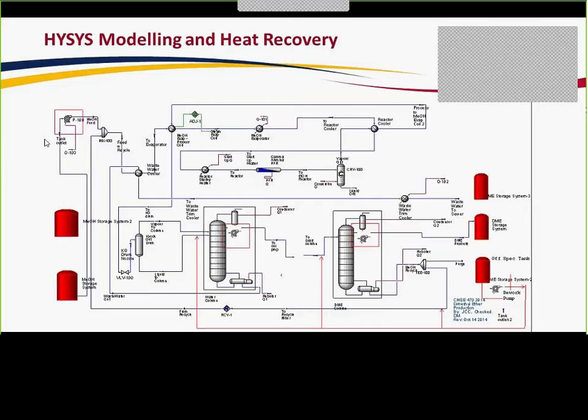In terms of heat recovery for the process, our heat exchanger network ended up going through a series of revisions, but we ended up using 3 different heat exchangers. We also have one heater, which is just before the reactor. It's only used during startup, to increase the temperature of the reactants as they go into the reactor. We also have one cooler, and it's used to decrease the temperature of the process wastewater as it exits the process into the sewer or the environment. The benefit of using these different heat exchangers is to lower the utility cost, which makes the project more economically feasible.